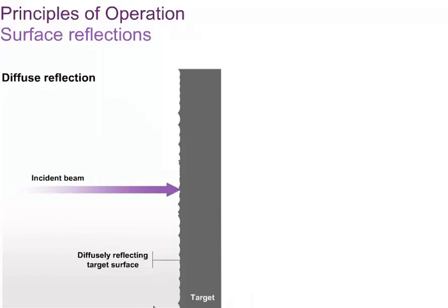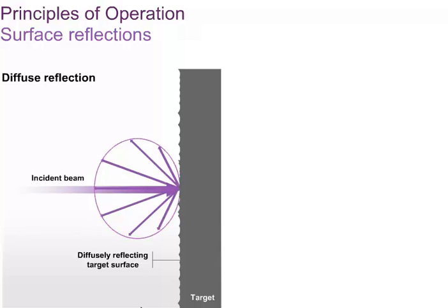Most surfaces will have diffuse reflectance, and therefore at least some of the light from the laser is always returned to the detector. It is diffuse reflectance that allows the laser level transmitter to measure the distance to granular materials that present a cone-up or cone-down surface. This is a unique advantage of the laser level transmitter.